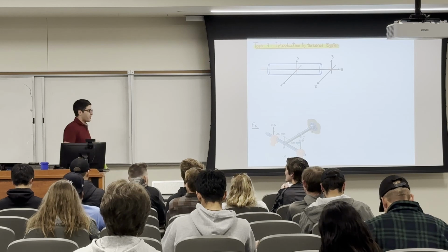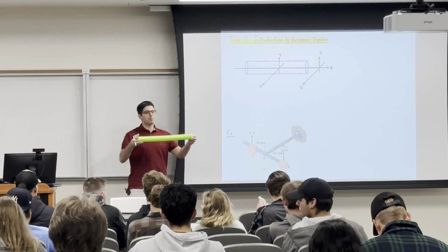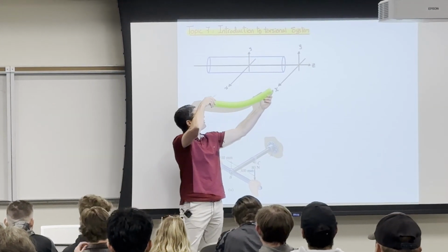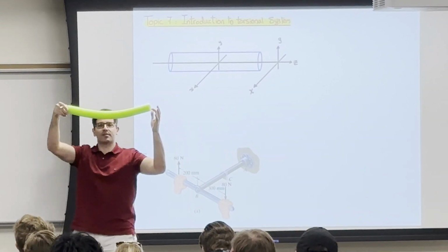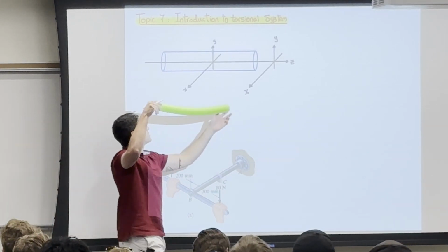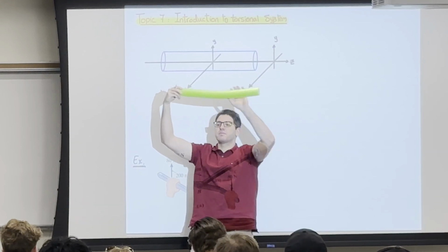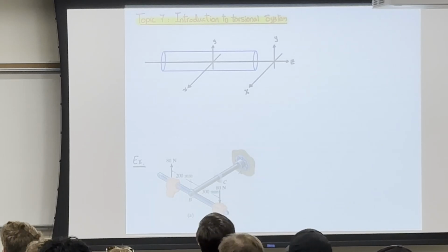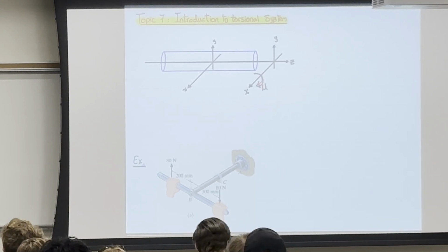So I will start first with asking you some questions. If I have a beam like this, and I apply a bending moment like this, so I'm applying a bending moment around x. So I'm pushing around x. What is this thing going to bend about? Which axis? If I'm using those axes, I'm bending it like this. So what is the axis that this beam is bending about? X. So if I apply a moment about x, like here, that's what we call Mx.